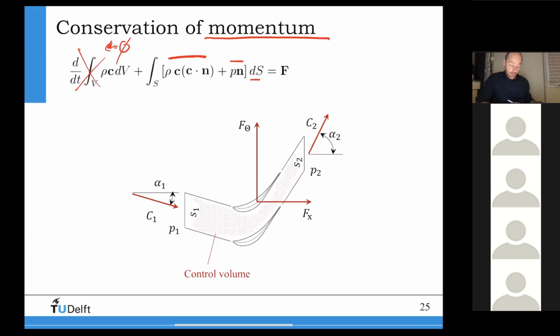Multiplied with the surface here, and then you get the force F, force balance equation, which you can derive even from Newton's second law. F is m times a. And so if you derive this for a fluid, you see all of these complicated things here. But now, since this is a vector here, this is a dot product. Rho times Cn is nothing else than the mass flow here. This thing here and this thing here is the mass flow.